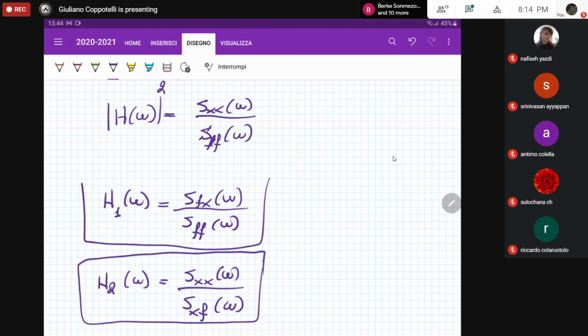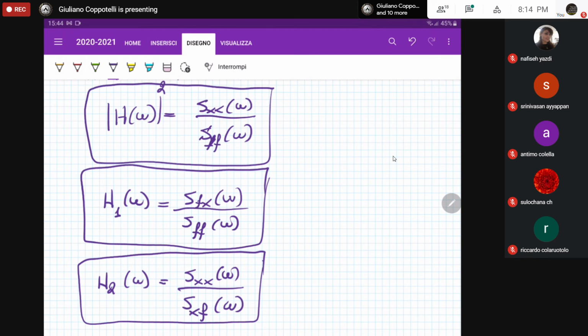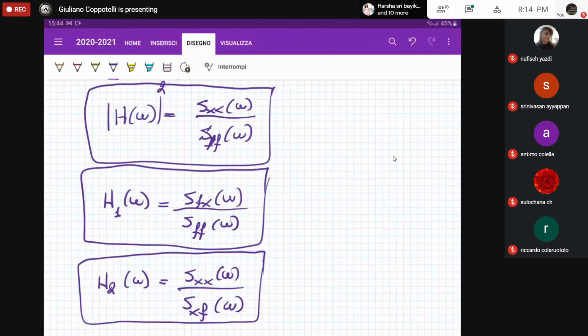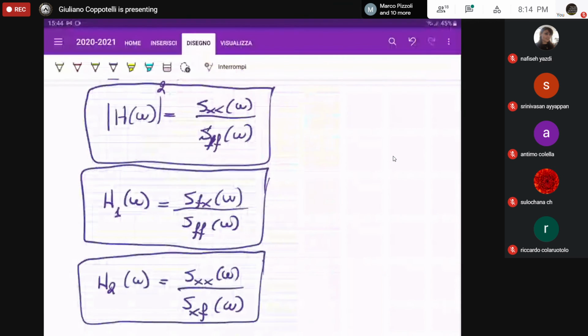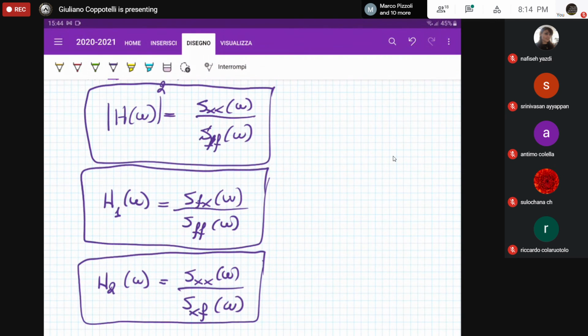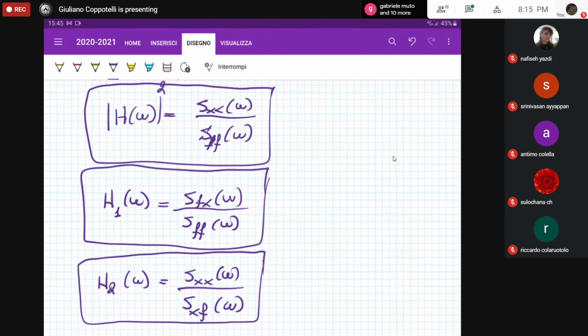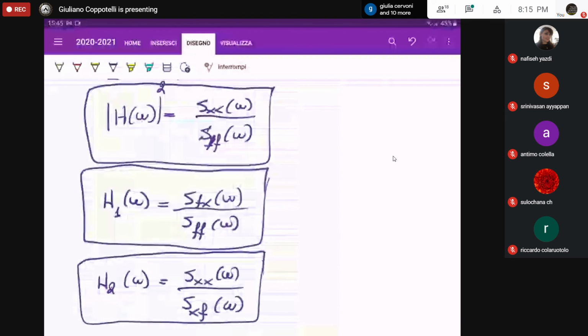As you can see, we can estimate the properties of your system just by using these three equations. All these three equations are referring to the input and the output measurements through the information of the power spectral densities. And we know how to obtain that just by considering the signal using the Wiener-Khinchin theorem, and therefore, instead of considering the expectation operator, that is the ensemble averaging, we are going to the time averaging if the system is excited by a stochastic ergodic system.